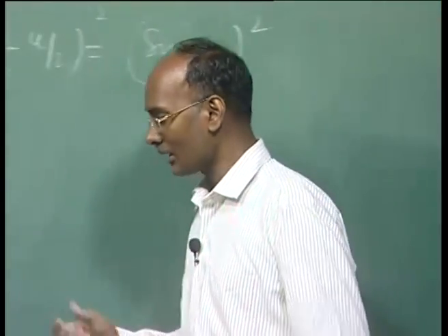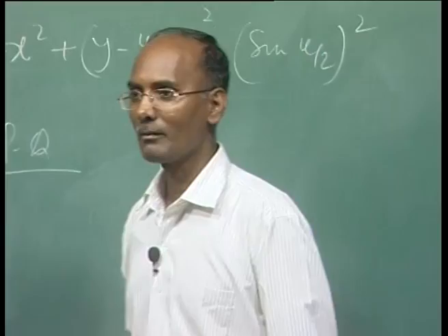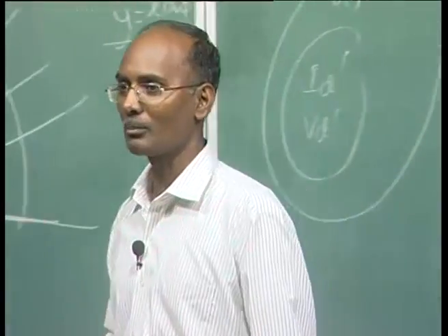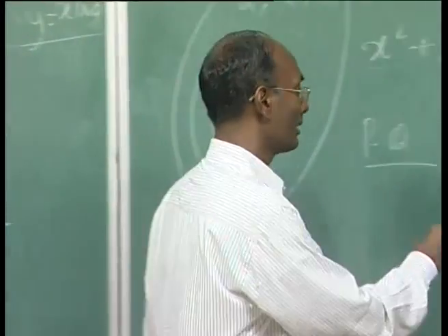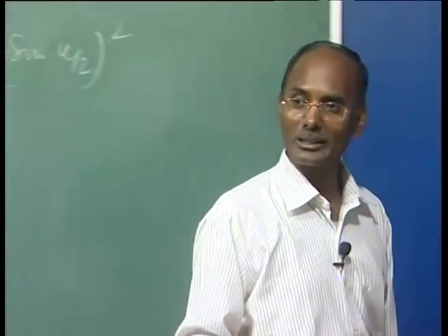In lecture number 9, I introduced another variable. Gamma was already coming all the way till our 3-4 valve conduction mode, and then I introduced zeta, the commutation margin angle, and how these angles change in inverter operation.